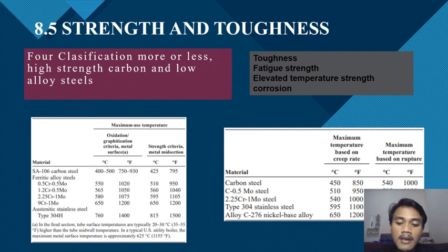of surface discontinuities or decarburization, the loss of carbon from the steel at its surface by reaction with the furnace atmosphere during processing of the heat treatment, improving surface finish, and controlling the details of the fabrication and fastening procedures to minimize stress concentration, and control of the protection against corrosion.